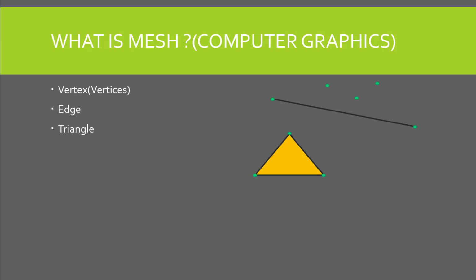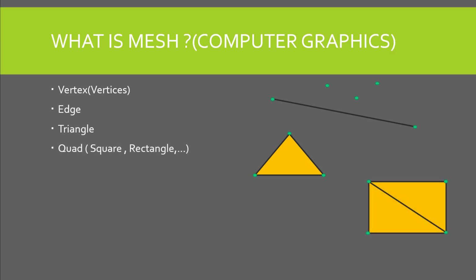The triangle will be the same concept, meaning triangle, and we call it the basic shape. Now, if we want to use a quad or a polygon, you will find we are going to divide it with lines to make it into triangles. We call the process triangulating the shape. For example, with a quad, we'll make one quad out of 2 triangles. Now polygons will be a number of triangles enough to cover the whole polygon.